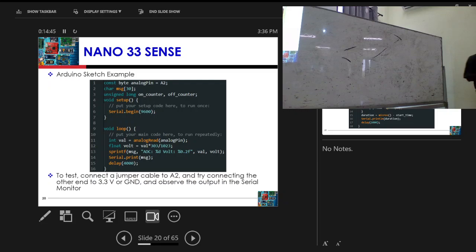Now next, this is where the technicalities come in. So I've gotten the analog value. Now I want the analog value in volts. I'm reading the pins, and you know that the pins are all about the voltage, either 0 volts or 3.3 volts. So I do the value I read times 3.3, and then divided by 1023.